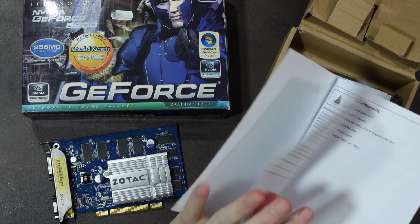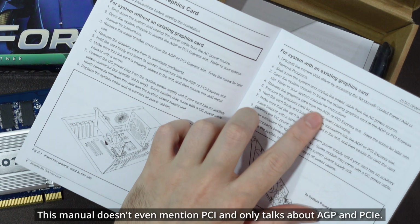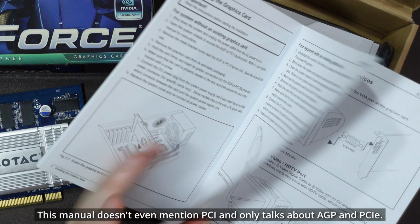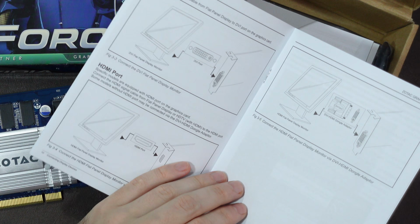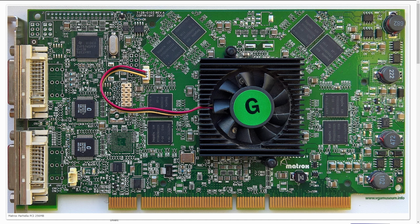Basically, you could say that your selection is getting extremely limited for PCI graphics cards for 5V systems around the year 2000, and thus also expensive, and you should probably rather consider AGP. Before we continue with AGP cards, let me briefly mention that there are also long 64-bit PCI slots and graphics cards for that. But while they do exist, they are exclusively for workstations, which is why I will not go into more detail there.